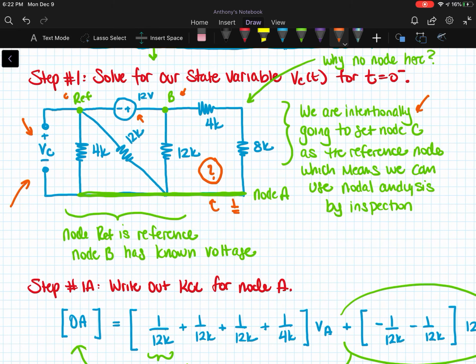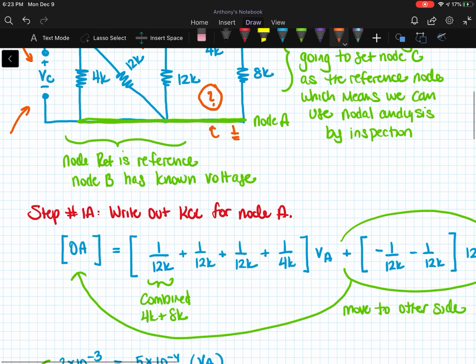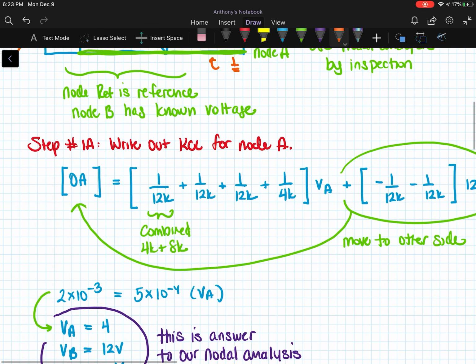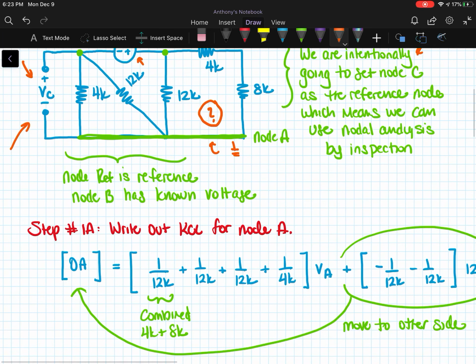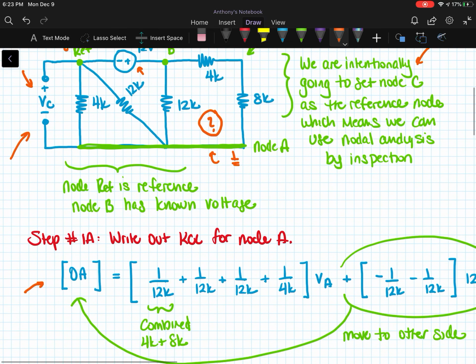And again, these are the kinds of things that you should have at least relatively fresh in your mind so you can get through the circuit analysis parts of these problems: nodal analysis, mesh analysis, or using some combination of equivalencies. All right, so now what is this equation here? Where does it come from? It comes from essentially the by inspection nodal analysis method.